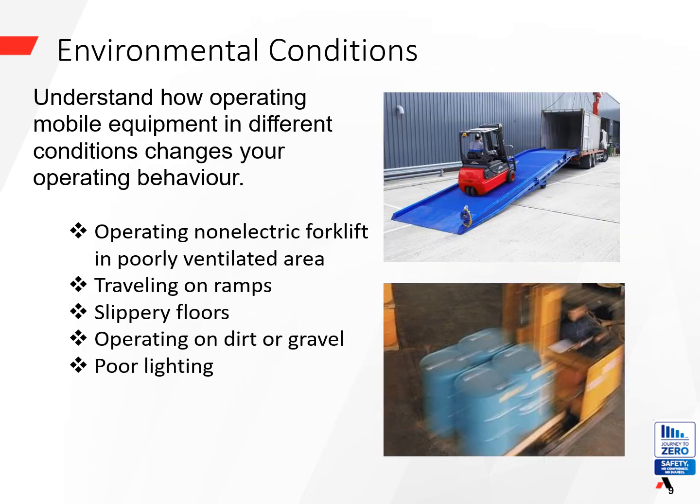Environmental conditions significantly influence mobile equipment operation. Operating a non-electric forklift in poorly ventilated areas requires a heightened awareness of potential hazards. Traveling on ramps demands careful maneuvering and control to prevent tipping or loss of control. Slippery floors necessitate reduced speed and increased braking distance to maintain traction. Operating on dirt or gravel surfaces requires adjustments in handling and stability due to uneven terrain. Poor lighting conditions require increased attention and reliance on equipment lighting for visibility.